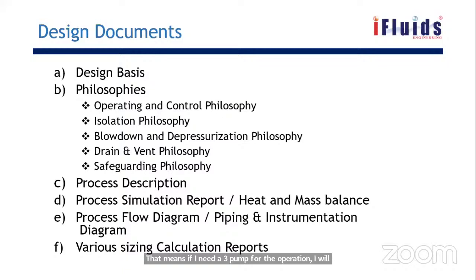So these things will be defined in the isolation philosophy. For maintenance, we need to go for isolation. Whether I need to go for a single isolation valve or two isolation valves for isolating a pump, these things will be captured in the isolation philosophy. And for the drain, whether I need to go for a single isolation valve or double isolation for the drain, all those things will be captured in the isolation philosophy.